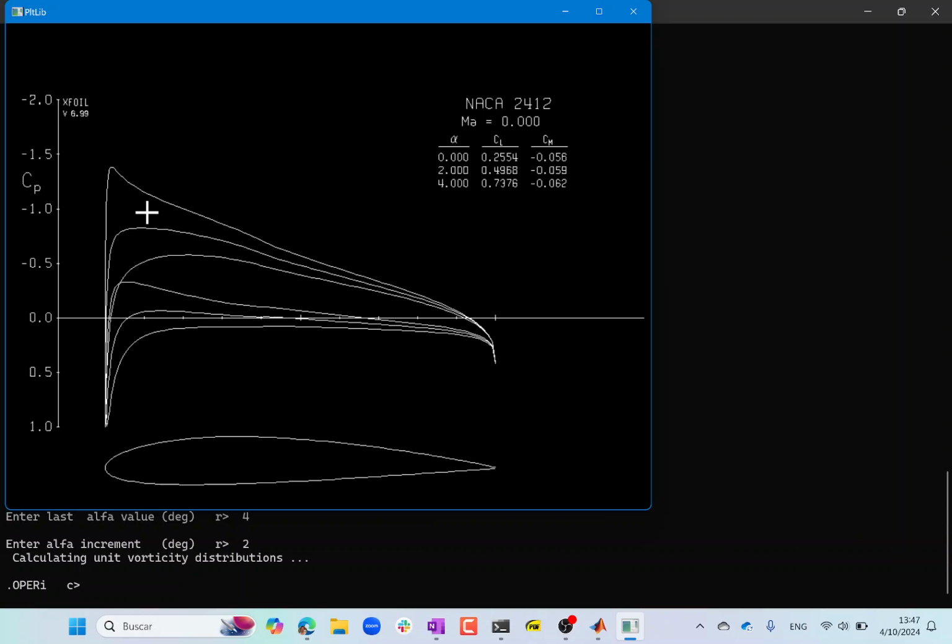Yeah. I want to flip this, but it only allows between -90 and 90. You want to flip which one? The angle of attack or what? This is like this thing I want to flip. Oh yeah, so for the airfoil it doesn't allow you to have a negative camber, but you can just reorient yourself, right? Think about this direction as the upward direction. So you basically just want this airfoil to generate negative lift. Make sense? If you put it at, let's say, -5-degree angle of attack, right? It's going to be generating negative lift. Oh, okay, CL is then already negative. Okay.